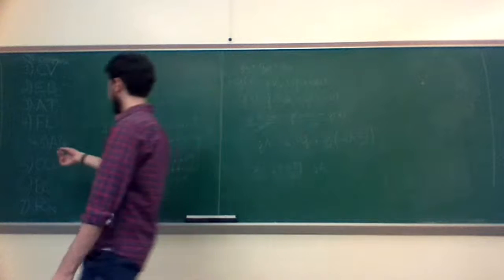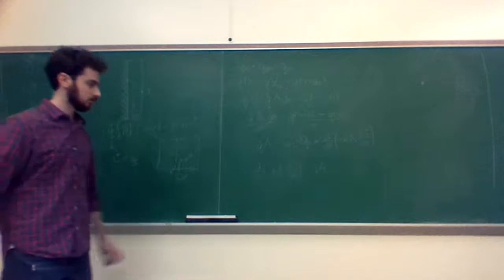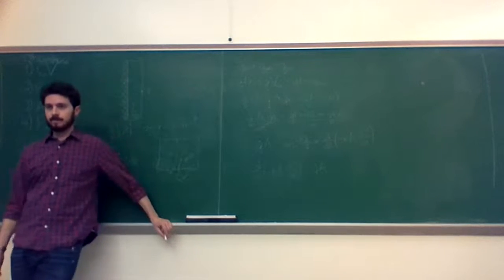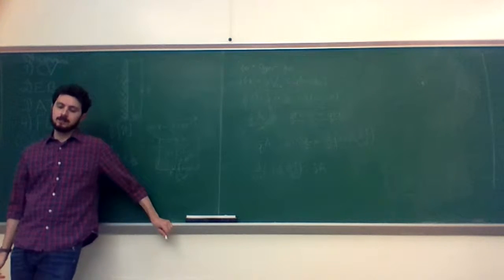But step 4.5 is assumptions. So what assumptions can we make that are going to make this calculus workable? A is constant, k is constant. Constant thermal conductivity, constant surface area.